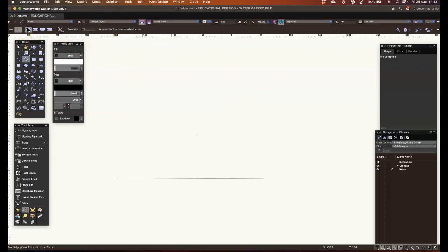So the left control line mode, you can see there's a little arrow there, so that means that if I click left to right, and again, a little tip, if you hold down shift, you lock. Even if I'm not on constrained, if I hold down shift, I'm locking it to one of the previous angles. So that's a good tip there. I'm holding shift at the moment.